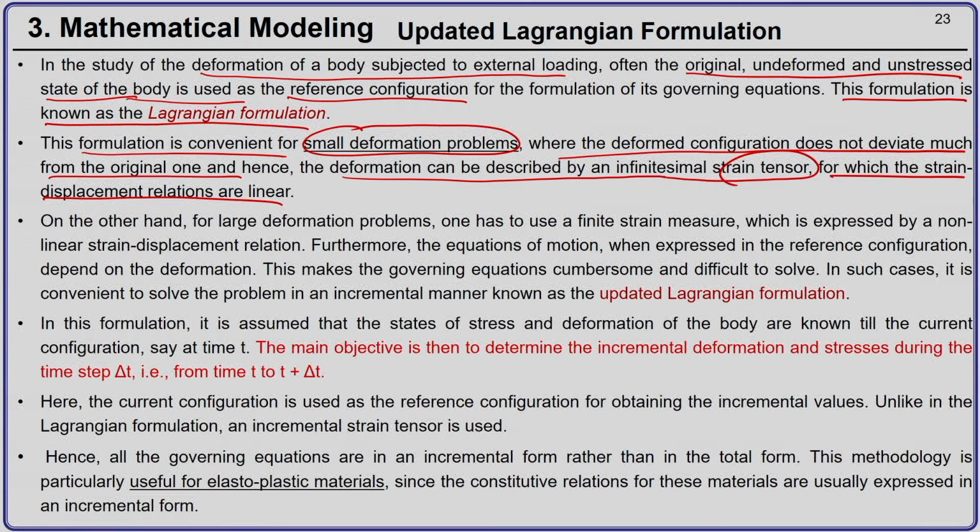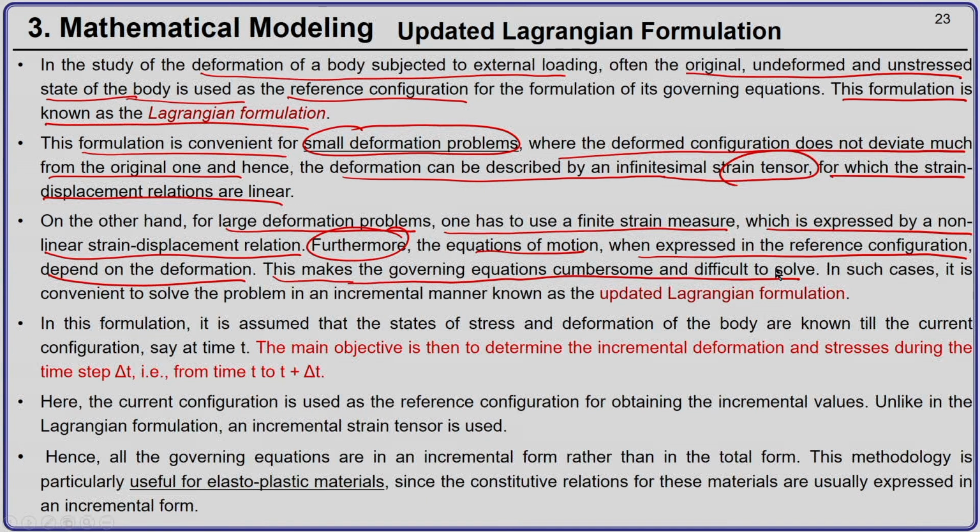On the other hand, for large deformation problems, one has to use a finite strain measure, which can be expressed by a nonlinear strain displacement relation. Furthermore, the equation of motion when expressed in the reference configuration depends on the deformation. So, if we use Lagrangian formulation, this will make the governing equation cumbersome and difficult to solve.